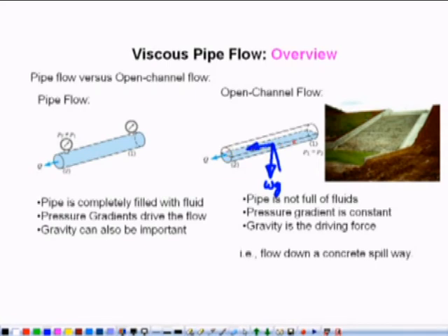So here we don't have a pressure gradient. What is the pressure here? Atmospheric pressure. What is the pressure here? Atmospheric pressure. So what is the gradient? The pressure gradient as such is 0. There is no pressure gradient, but because of gravity there is a force acting in a downward direction which is responsible for applying shear stress on this fluid.